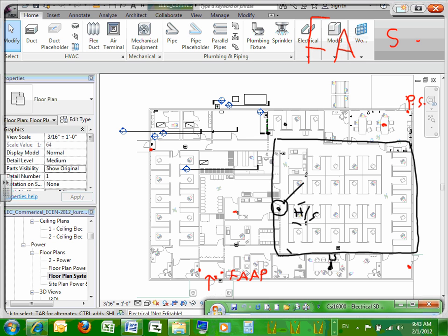Smoke detection throughout the entire building. Again, not a requirement at all. In fact, a lot of people will try to deter you from doing that, because smoke detectors, when they're not required, are more of a false alarm trigger than anything. When they get dirty, after the system's been installed for 10 years, if a building owner isn't maintaining their smokes, you might get tons of false alarms.